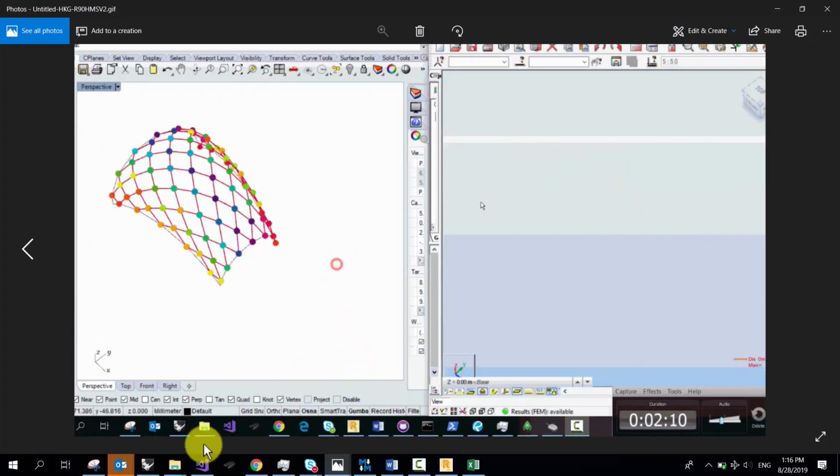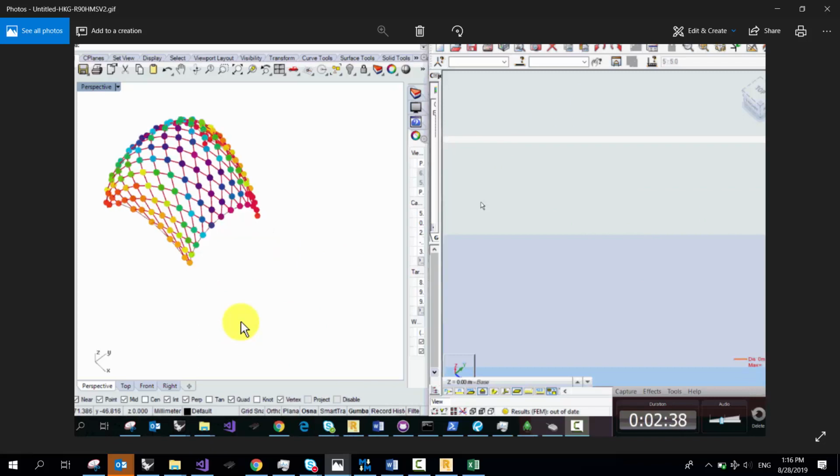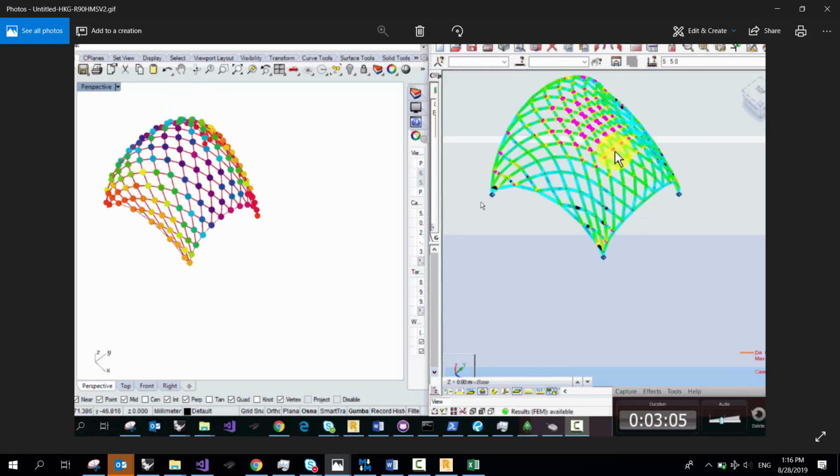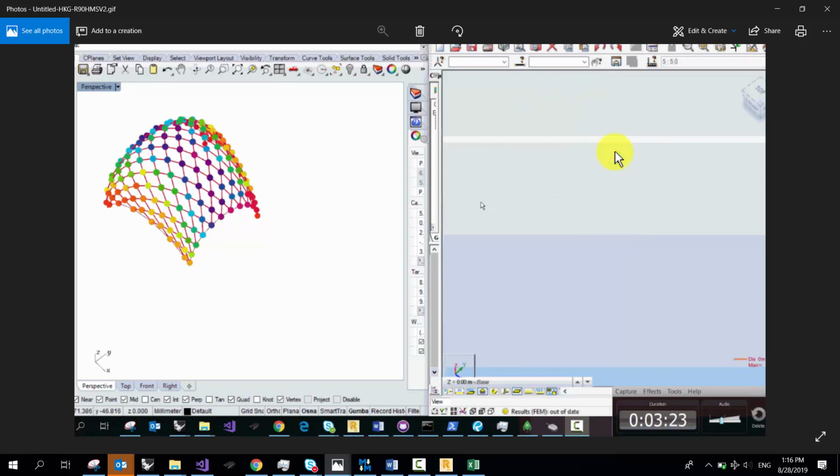So I recently had something that was kind of like this, where I was just all night sending over robot models into Robot. They would obviously change in Rhino, right? And then they'd show up in Robot, they'd run, I'd extract the results, right? And you could use this to optimize, as you say, the best location.